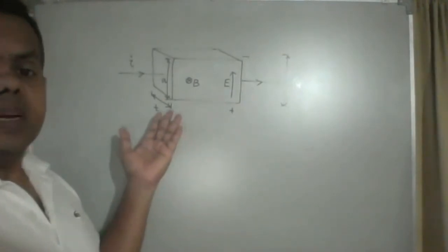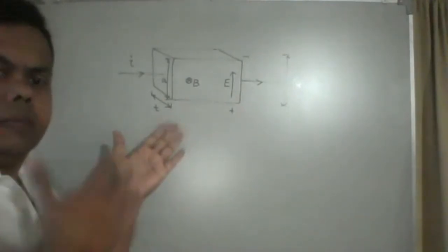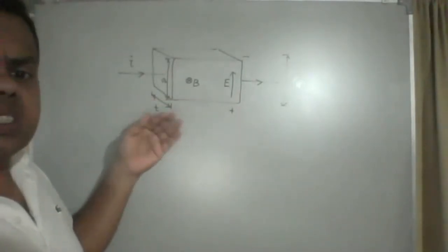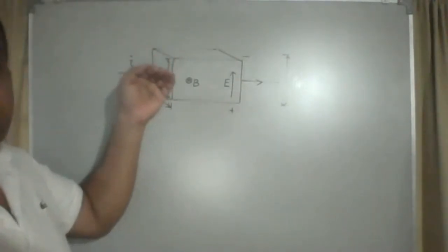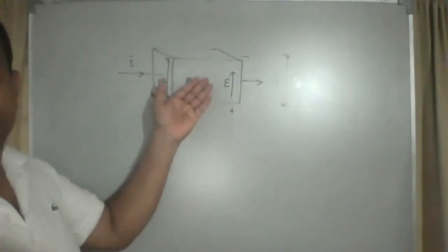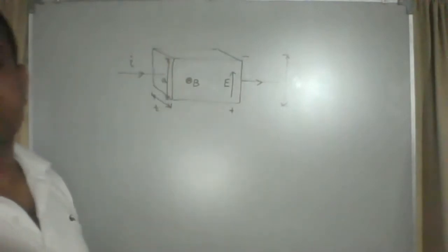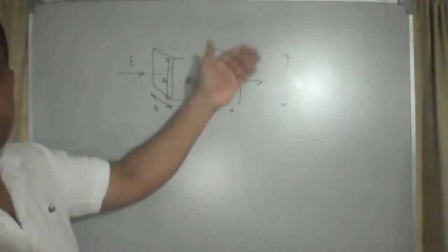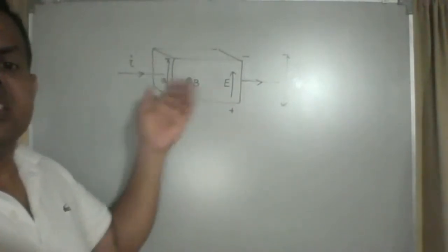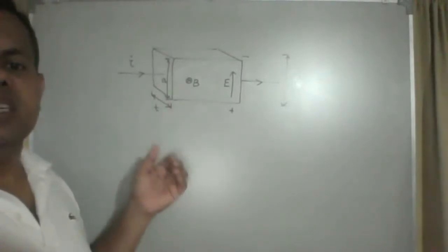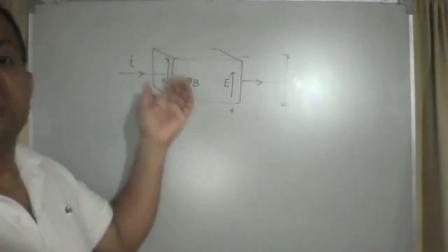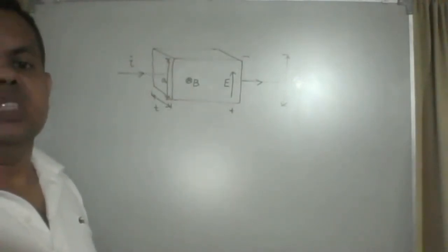If we maintain a magnetic flux through the conductor perpendicular to the conductor, the drifting electrons will be shifted upwards due to magnetic force. Therefore, an electric field is created directed upwards. Voltage difference is also created as shown in the figure. Once the steady state has been achieved, the magnetic force on the electron will be equal to the electrostatic force on the same electron.